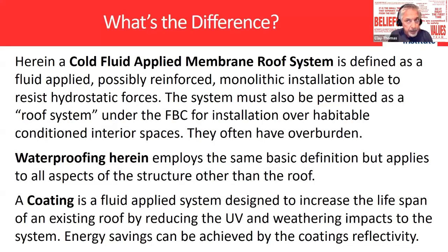When I went to do a coating job in the Tampa market and went to get a permit, I brought them my moisture survey. They asked me, what's that for? And they gave it back to me. After spending $2,500 on a moisture survey, I was not only a little embarrassed, but I learned a good lesson. But at the end of the day, as a contractor, I wanted to do my due diligence regardless, because I don't want to apply any type of coating over a wet substrate.